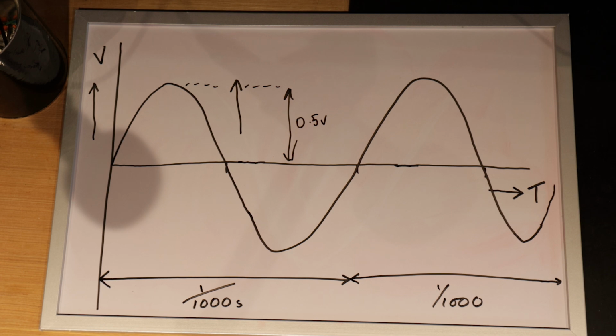You can then check the output of that tube and see that it's been increased in volume. You can then follow that through the tone stack, and eventually you can find where the signal disappears. That gives you an idea of where the fault might lie.